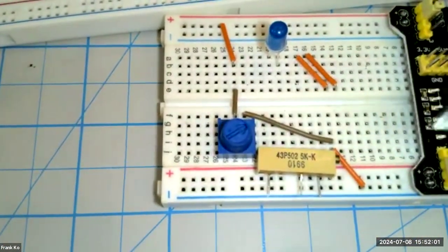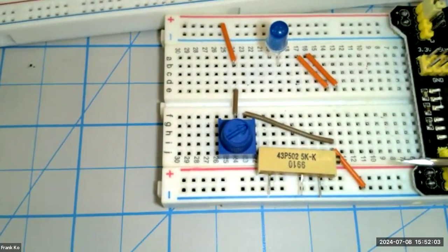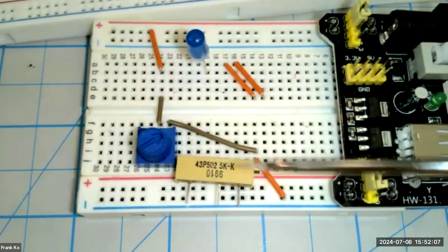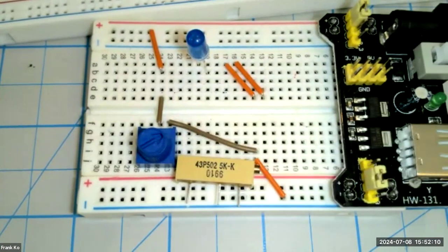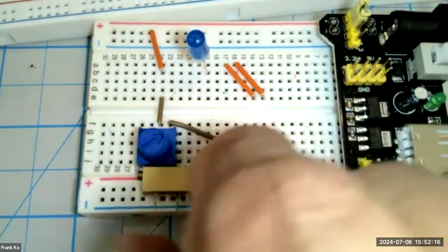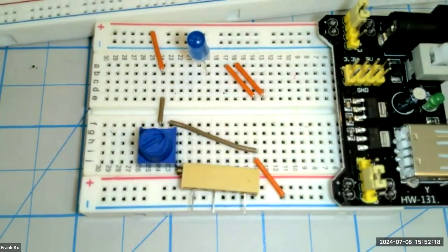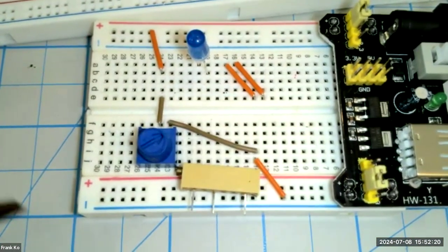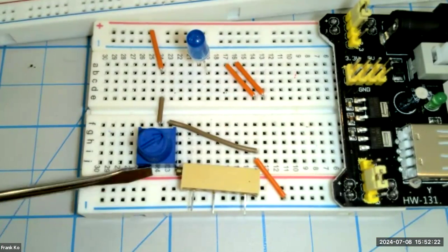Why? Because my screwdriver has to come from this side, and I happen to have some hardware like this power supply that's in the way of my screwdriver. So if I wanted a 5K ohm pot and I wanted this specific pot, I would rotate this way. Okay, insert it in the board, and that way my screwdriver would come from this side, do the turning in